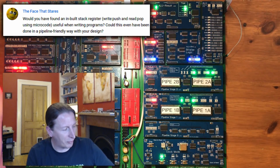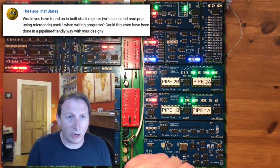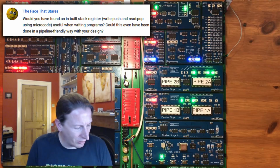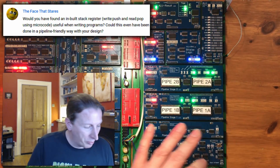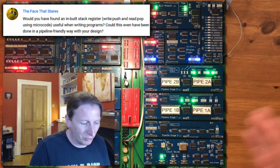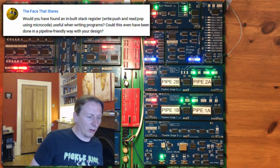I've got a stack pointer, and I can push and pop any of my 8-bit registers as a standard operation. It takes 2 cycles because I can't fetch a new instruction while the memory op is going on, but it's there and it works, and I've made good use of it, and it's actually essential. I really needed those stack operations to be able to write complicated programs.